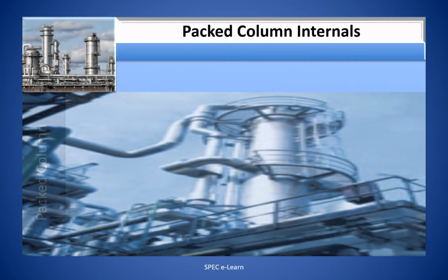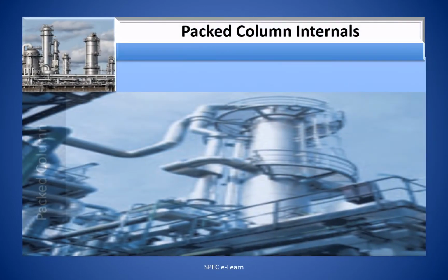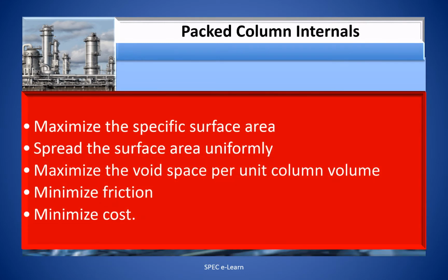To produce packing surface with maximum efficiency, the design focuses on the following characteristics of the packing. The design and development of packing focuses on the following aspects. Maximize the specific surface area, spread the surface area uniformly, maximize the void space per unit column volume, minimize friction, and minimize cost.